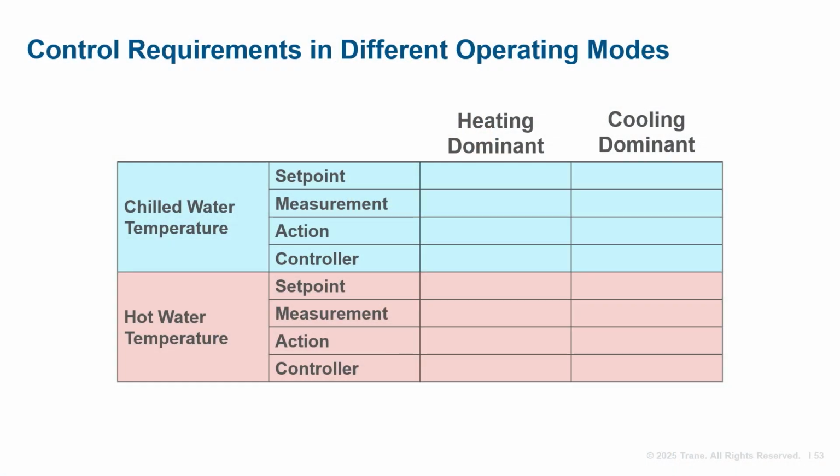Whenever the system includes different operating modes, and especially if the controller assignments are changed in each mode, then it makes sense to create a mode table. A table like this may help to avoid missing sensors or modes where critical set points are not regulated. As the project matures, the controls engineer will incorporate this information into the system sequences of operation.